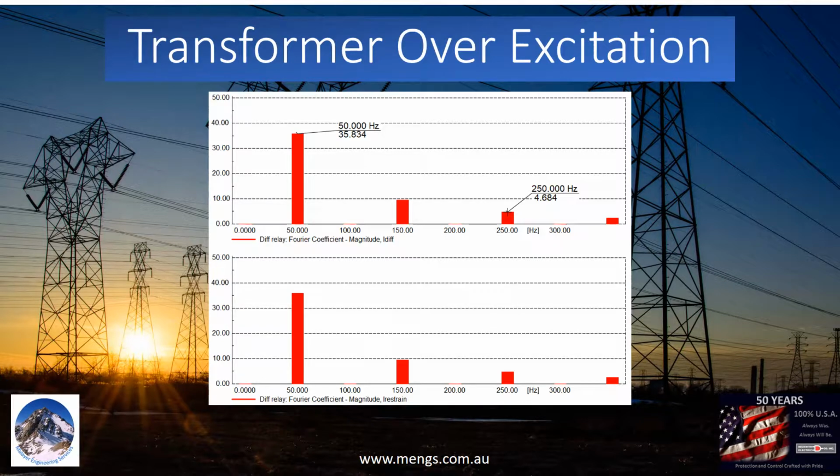During a heavy fault, current transformers get saturated. As we see, the saturated transformer is generating the fifth harmonic. The lower limit for the fifth harmonic blocking is to avoid relay blocking during the fault. During the heaviest fault, the fifth harmonic content of the differential current is about 13%. So the setting has to be somewhere between 13% and 22%. 15% is the advised setting for this system.